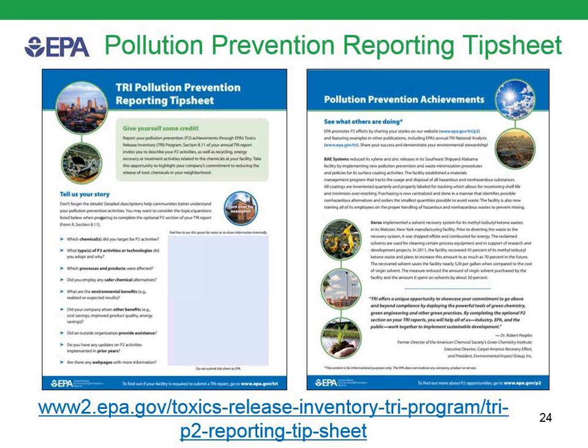So the most preferred is if you have something like continuous emissions monitoring. So sometimes we'll get different degrees of monitoring data. If you're required to monitor releases under other environmental statutes, then you use that for your TRI reporting. If you're not, then in a lot of cases, EPA has published emissions factors, and you use those to make calculations. But there's a whole kind of hierarchy. If you have this information, use that. If not, you can use this, and it goes down to sort of just reasonable estimates using best engineering judgment. But most of the time, you'll have some kind of data that you'll base it on.